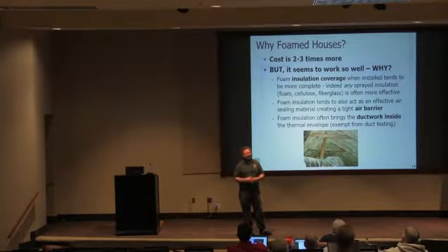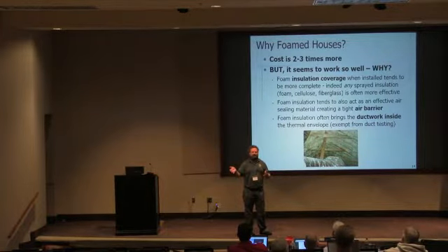Take out the drywall, put more foam up, do it with a good mix, do it when the temperature conditions are right, and fill in the gaps that were created by the poor job that was done the first time around. It sucks.